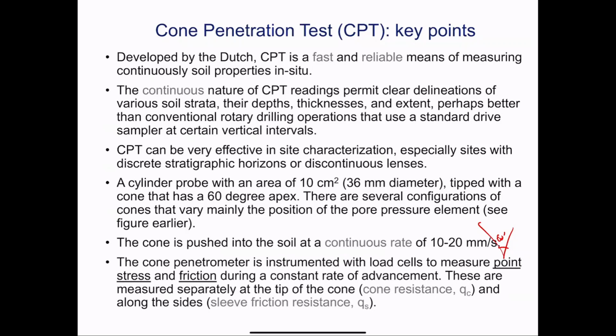The cone penetrometer that I showed you is heavily instrumented. You have load cells, which are full bridge strain gauges, to measure sleeve friction and tip stress. And you can also have piezoelectric elements to get the pore pressure. So these are just fancy words for measuring pore pressure, sleeve friction, and tip stress. And we'll talk about how we use these measured parameters to get geotechnical properties.